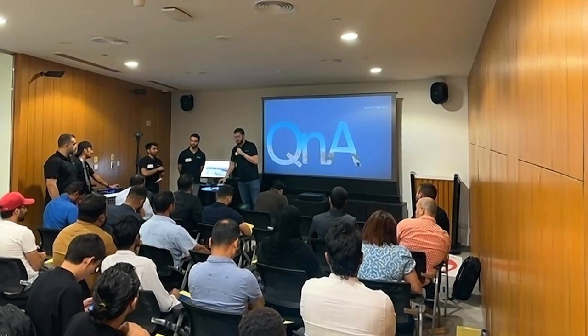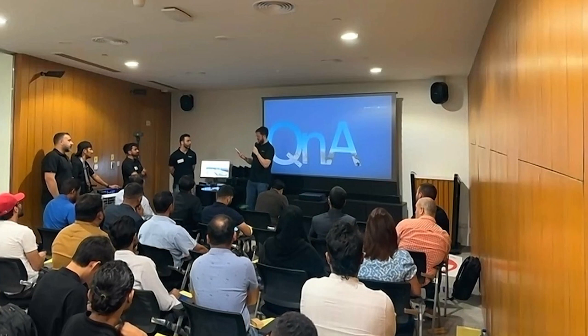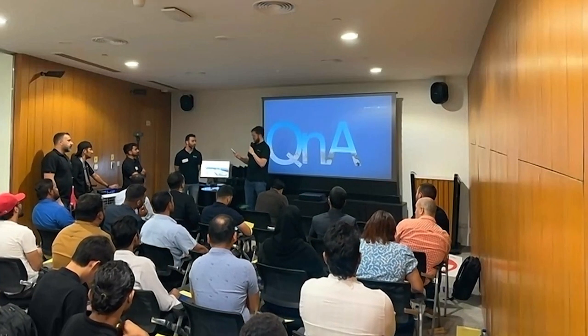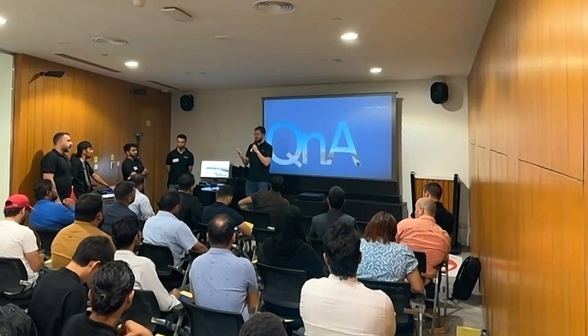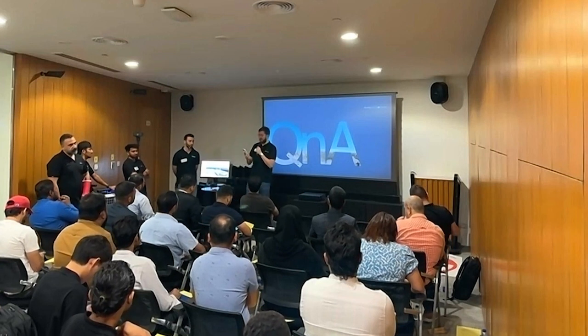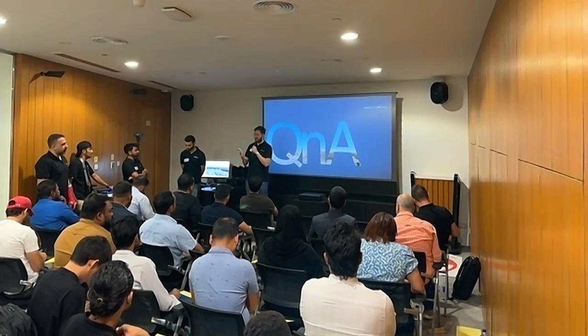One more question? Okay, can the Mavic 3 Enterprise do PPK processing using PPK processing software with static base station RINEX data? Can you use post-processing software using PPK? Yes, you can take your RTK data and process it using any third-party PPK processing software. You take that information and collaborate it maybe with ground control points to improve it. So essentially you are post-processing that RTK data. Yes, that is possible. Hope that answers your question online. Thank you very much. Any other questions?